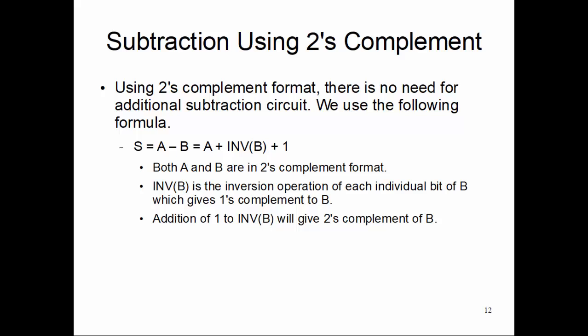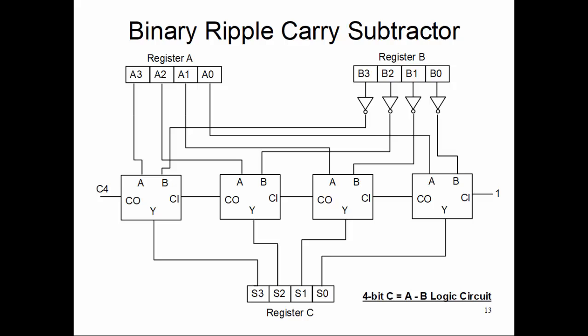So we got a bit amount like 15, for example. What we need to do is make a minus 15 representation, a bit representation, which can be easily done in 2's complement format. If we assume all these bits are represented in 2's complement, from a given amount, we invert all the bits and add one on top of that inverted bit pattern.